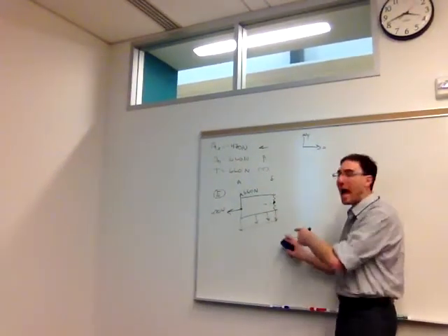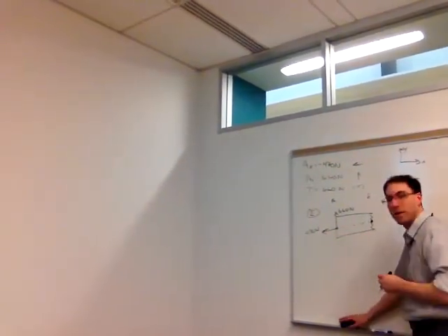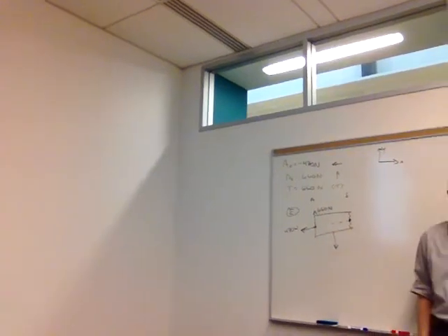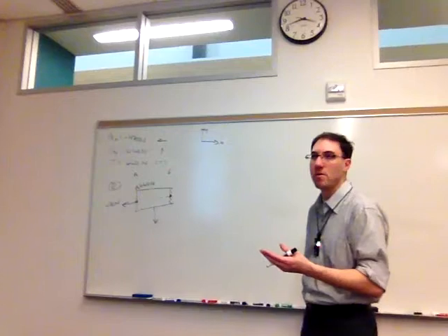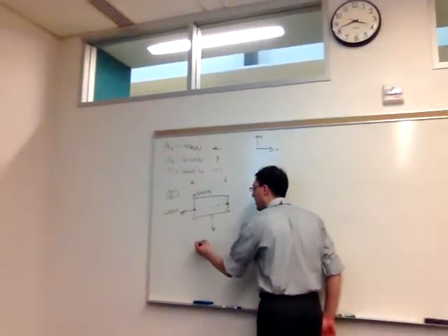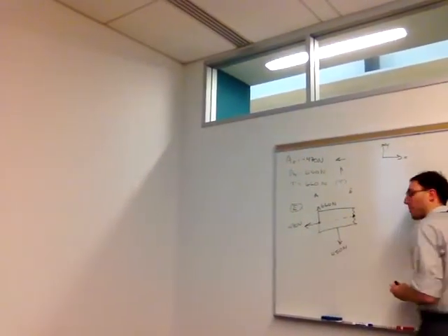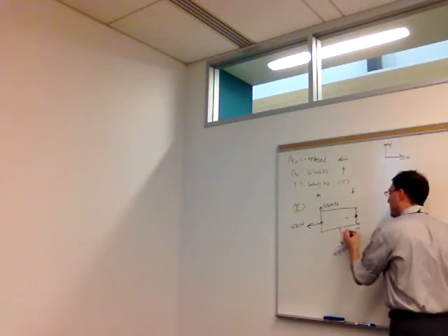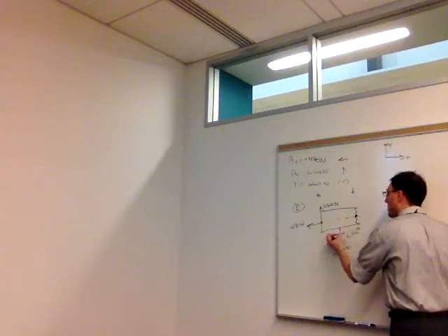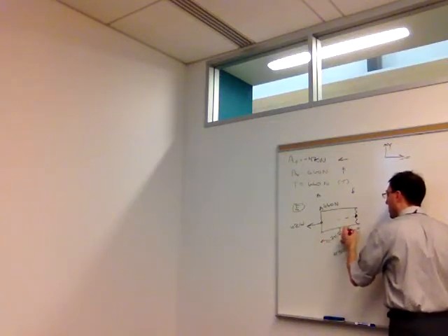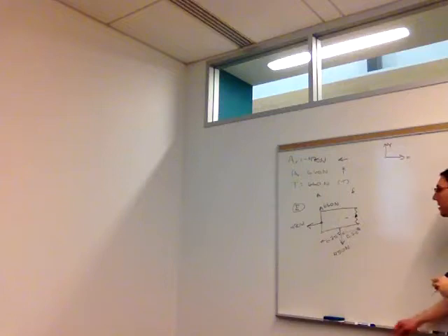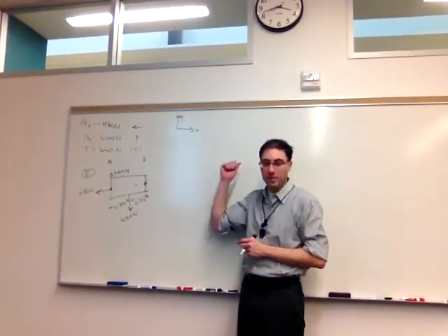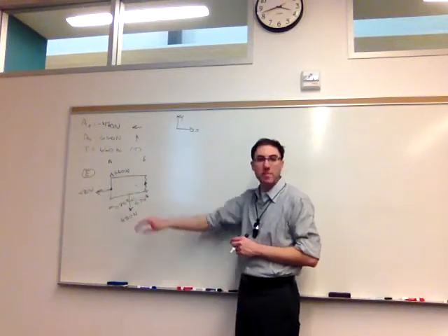Once it's in this picture, now we can simplify it down to a point load that will be easier to work with. So the equivalent point load from that distributed load is going to be the 300 newtons per meter times 1.5. So equivalent of 450 newtons that comes from the distributed load and acting at the middle, since it is a uniformly distributed load. So the distributed load in this picture just simplified to the point load, and it will give me the right answer within this picture.